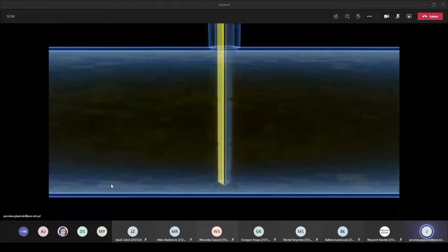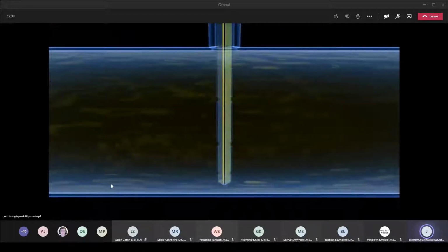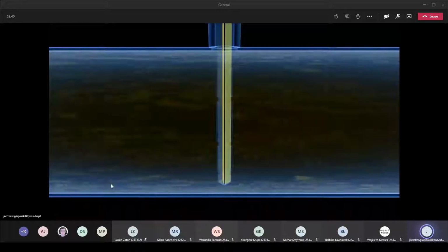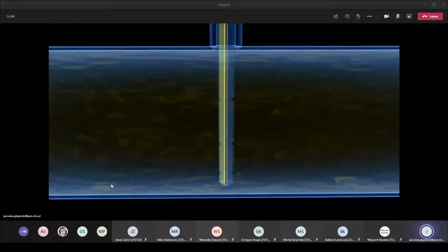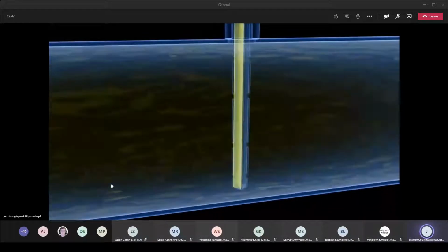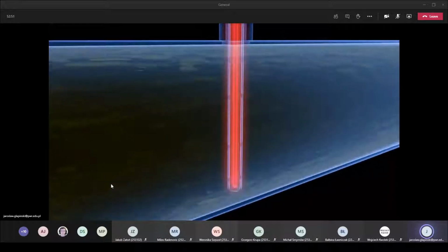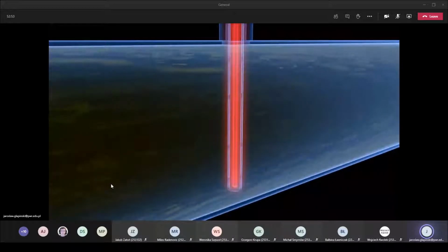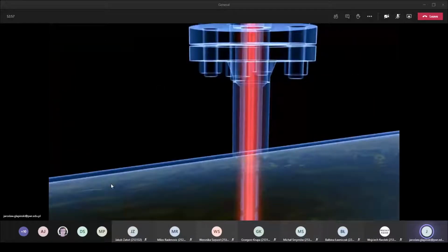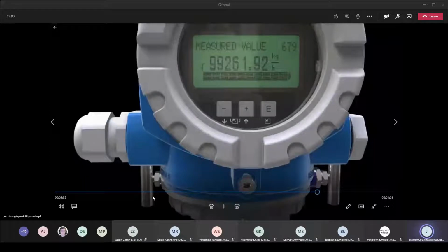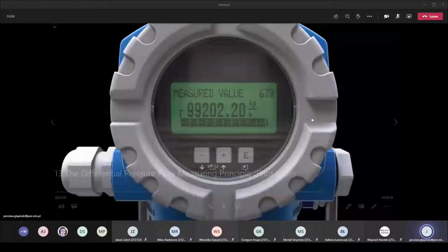Pitot tubes are able to register the flow in both flow directions. This means that balancing measurements, for example in gas pipeline networks, can be carried out at any time. Continuous improvements have been made to pitot tubes over the past decades. Devices with a built-in temperature sensor, for example, together with a flow computer, can also calculate temperature-dependent mass and energy flows.